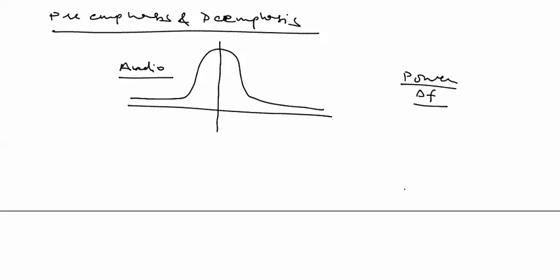Throughout the frequency range, power spectral density is not constant. It is variable. For the initial lower frequency components it is higher, and for higher frequency it is very low. Noise is also not constant. For FM, the power spectral density of noise is parabolic in pattern, varying with frequency. In AM and PM it is constant, rectangular. In FM it is parabolic. As frequency increases, noise also increases.